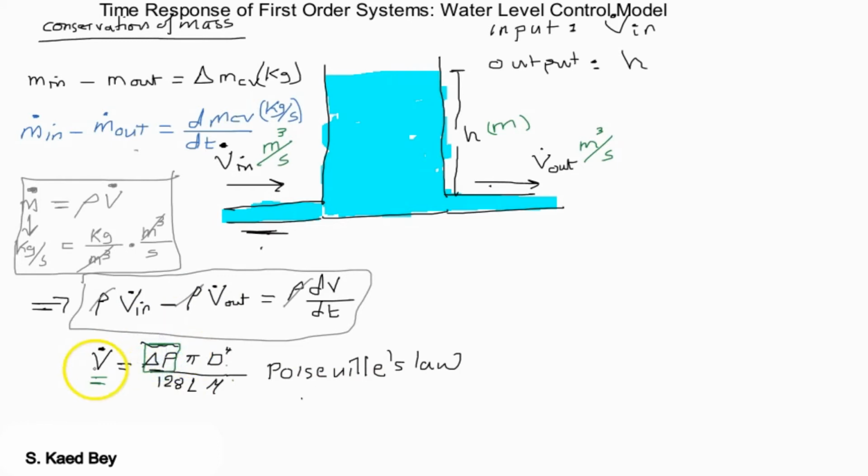So one way for an engineer to control the flow rate to the tank shown here is by adjusting the pressure. And if you have a static pressure head as well, in this case, this will dictate the flow output of your system. To make sure you are in laminar flow before you use this equation, you have to calculate what we call the Reynolds number. The Reynolds number depends on the density, the velocity of your liquid, the diameter of the circular pipe, or hydraulic diameter in the case of non-circular pipes, divided by the viscosity.